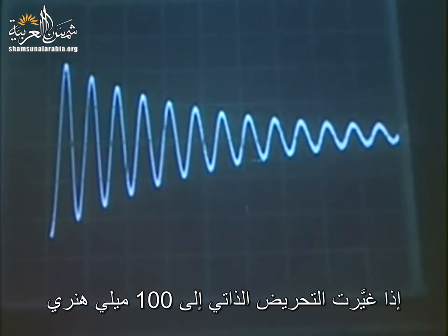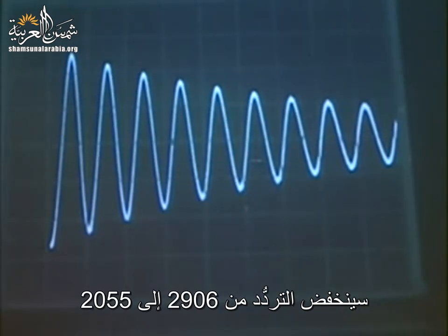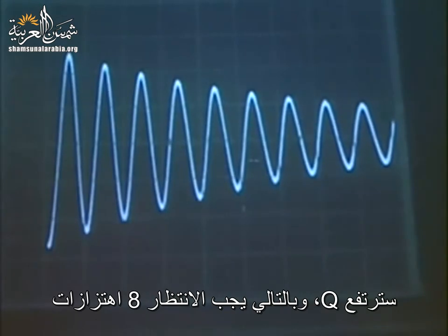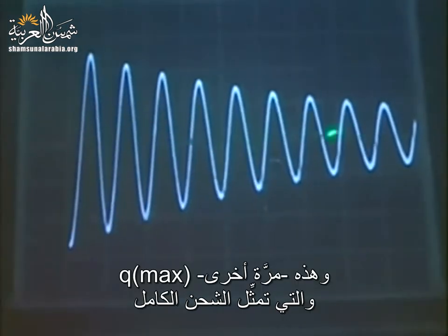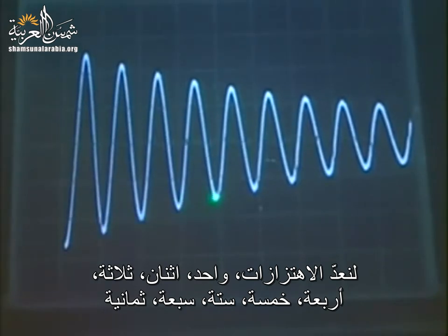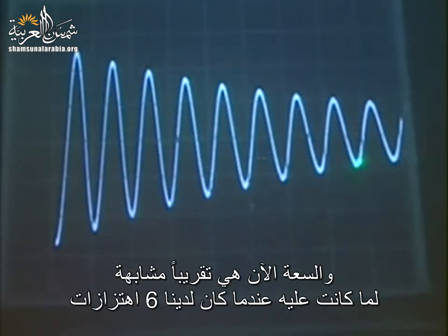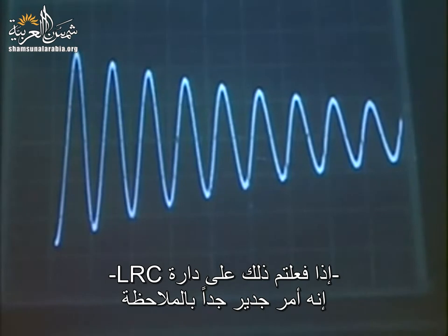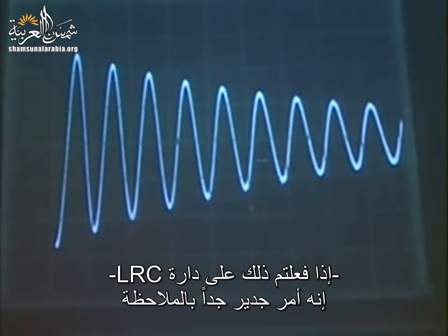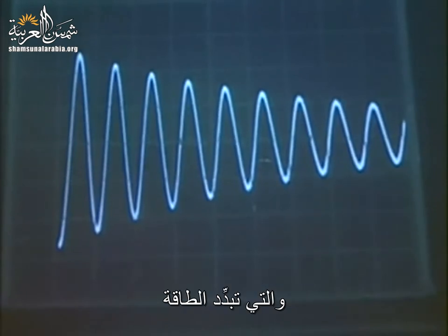If now I change the self-inductance to 100 millihenries, then the frequency goes down from here 2906 to 2055. The Q goes up, and now you have to wait 8 oscillations. So Q is 0 is on the left side of the bottom. This is again fully charged, Q max. And now we go 1, 2, 3, 4, 5, 6, 7, 8. And the amplitude now is roughly the same what it was before when we had 6 oscillations. So you see that this works like a charm if you do it with an LRC circuit. Really quite remarkable. It's a dying oscillation, and the damping is the result of the resistor, which is dissipating energy.